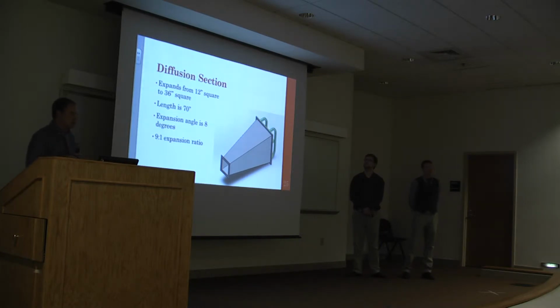For the design of the diffusion section, it expands from 12 inches to 36 inches square by a 9:1 expansion ratio. The overall length is 70 inches.